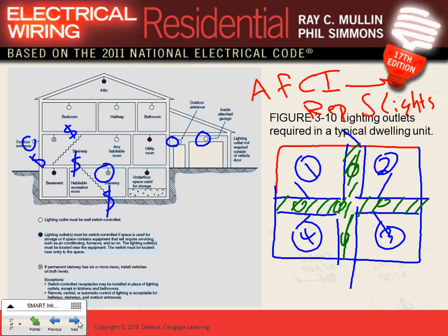Can you guys give me a thumbs up, Chad? We know how to circuit with the GFCI, and so we're going to lay out the receptacles next week and circuit them and assign a 20 amp circuit or 15 amp circuit or 30 amp circuit or 40 amp circuit to the circuits, as well as laying them out and deciding which one GFCI, which AFCI.